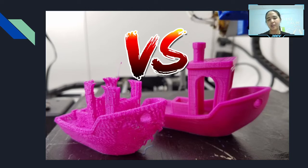Over here at the first object that you can see, it actually stopped halfway through the print and the extrusion is not flowing. This is normally caused by a blockage of the nozzle, or the flow percentage.